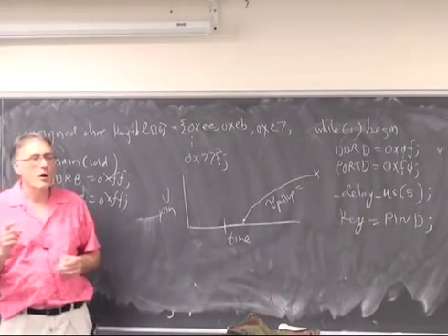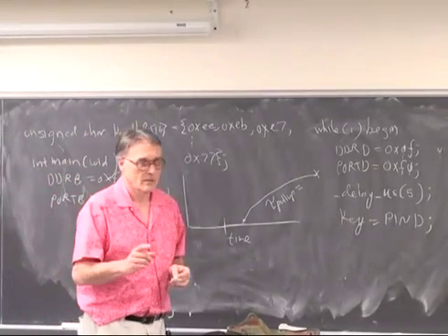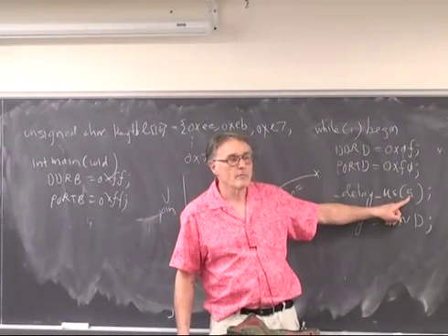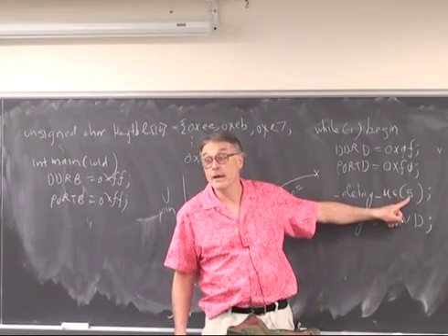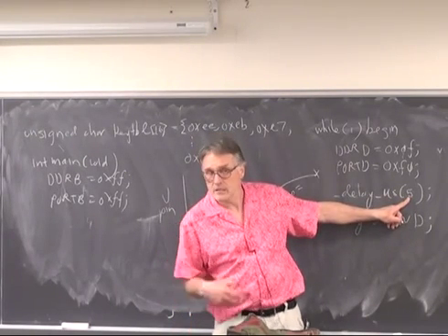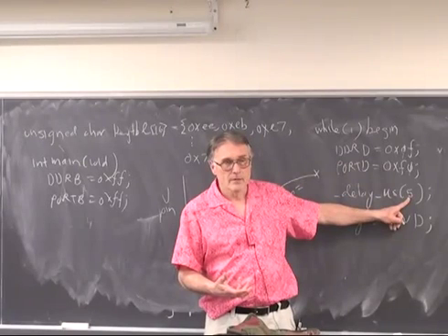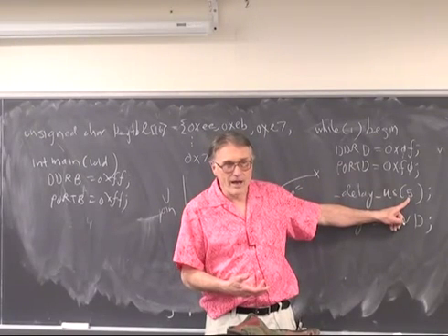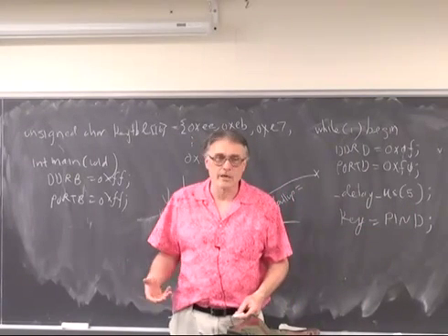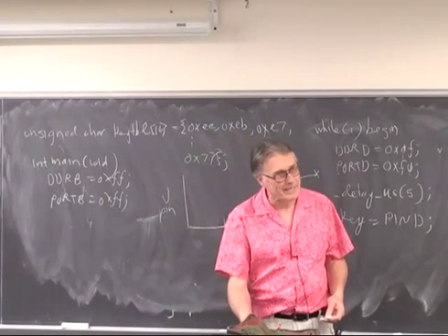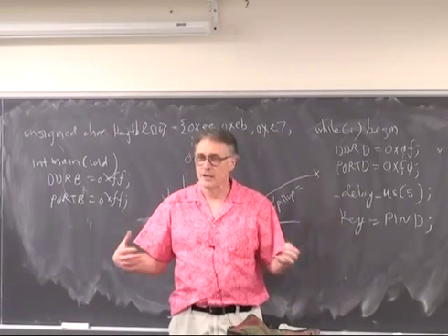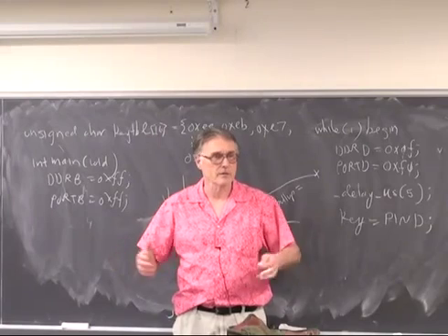And I strongly suggest that you take this demo code and you decrease this time to 2 microseconds, see what happens, to 1 microsecond, see what happens. It fails someplace lower than 5. But it depends on how long your wires are and how close your body is to the keypad, because depending on your surface area, you're about a 100 picofarad capacitor.